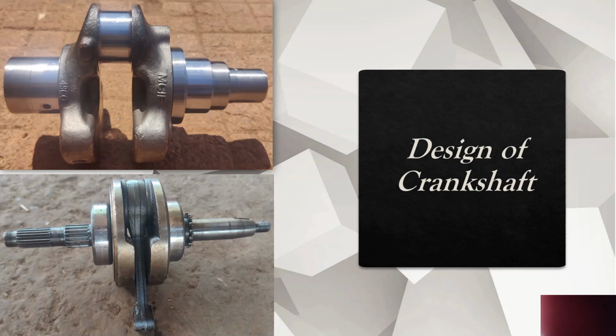Let's see the design of crankshaft. Crankshaft is the main shaft of an engine which is converting the reciprocating motion into rotary motion. So crankshaft has different components: left hand web, right hand web. Here is crankpin, left hand journal, right hand journal. At crankpin, big end bearing of connecting rod is connected.